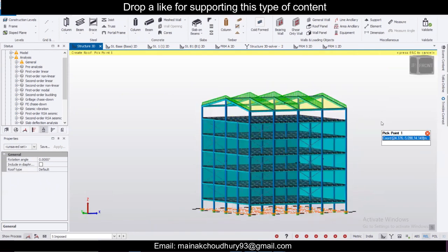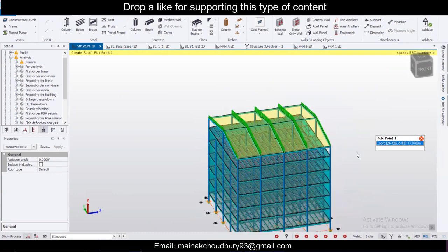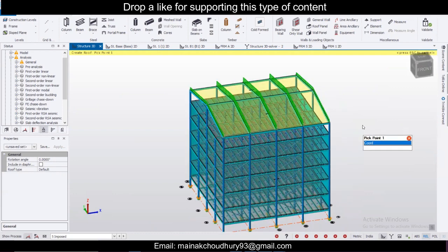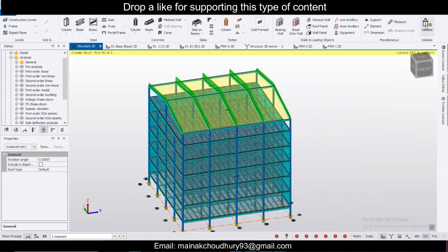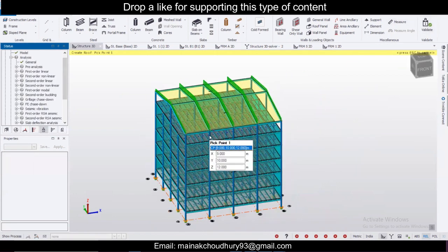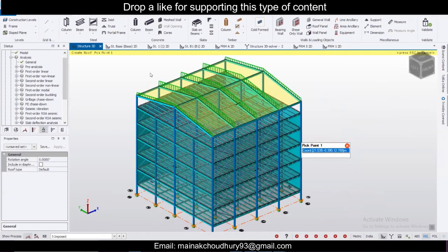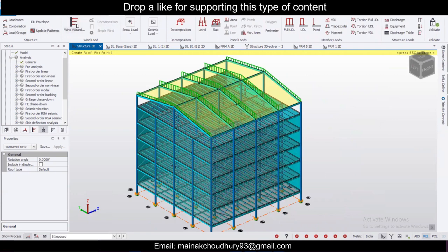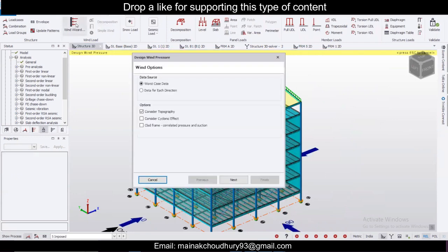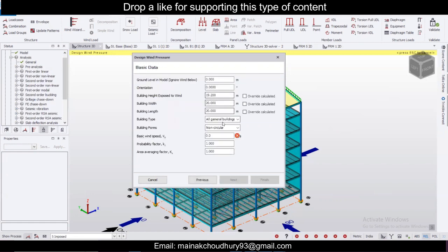So roof panels and wind panels have been inserted, and now we can click on validate to check the model if everything is okay. Okay, and then we can go to load and go to wind wizard. You will not apply seismic load, you just apply the wind load. Okay, so I'll go with data with each direction, the two possible ways. You can consider as per your country code. I'm just going as per the Indian code here.